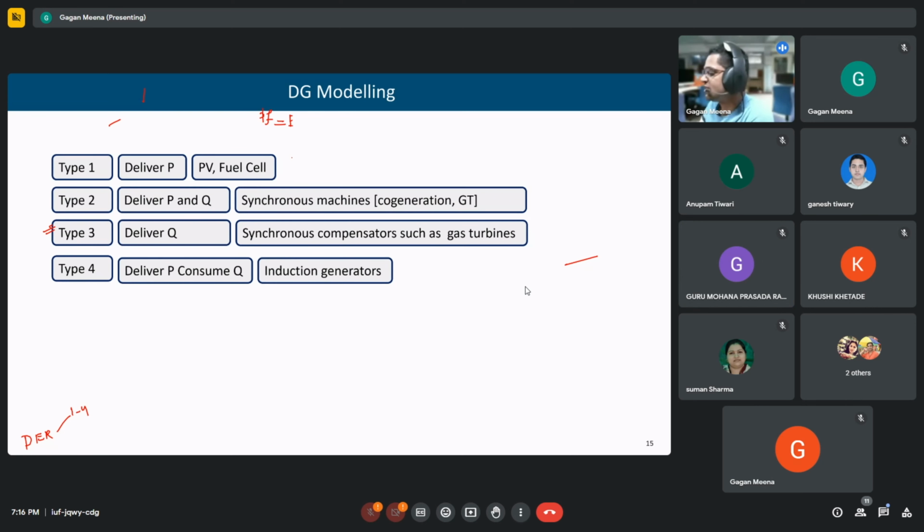No, no. In HVDC or whatever this is, if the generator is taking reactive power from the transmission line, that is why we want to compensate, so that we do not need to draw the reactive power from the transmission line. We can locally supply that reactive power. That is why we use a compensator. Because if we overdraw reactive power, then it will affect the voltage profile. The voltage will reduce at that point, at that bus. So we locally supply that reactive power so that the requirement from the transmission system reduces.